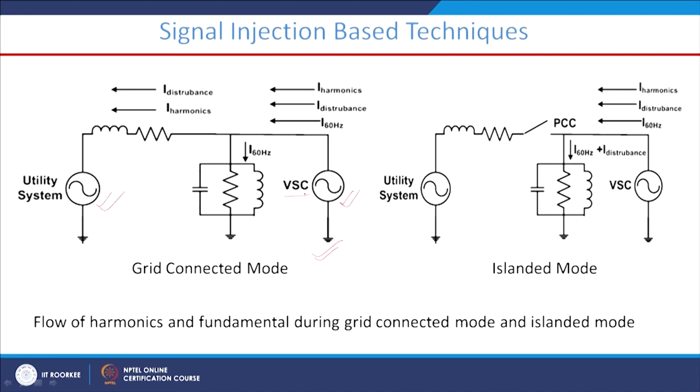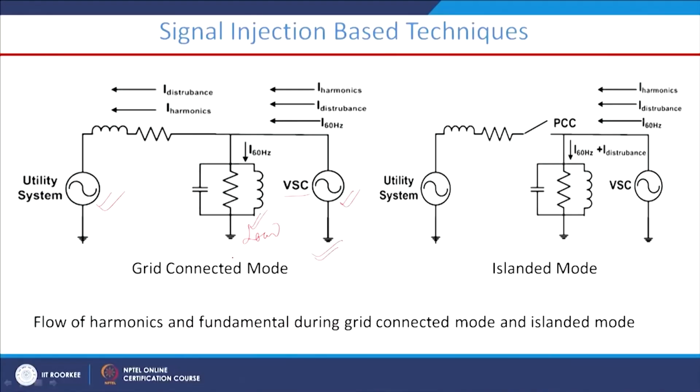VSC stands for voltage source converter system, used with solar or wind systems, and here this is our load. During grid connected mode, we inject I disturbance with a certain low frequency, let us consider 30 hertz.